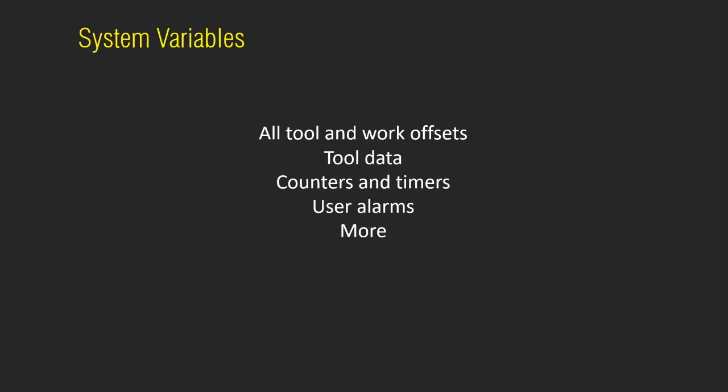I also list tool data there because we looked at that early in this webinar. The tool data is where I can set the approximate lengths and diameters, so I can provide a nice, easy way for the operator to just jump into the offset page and tool offset measure, and I've got my tool being touched off.